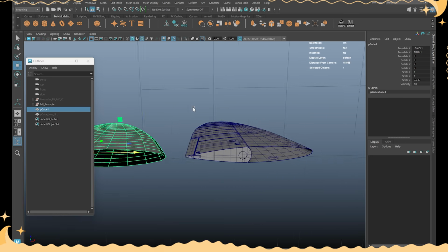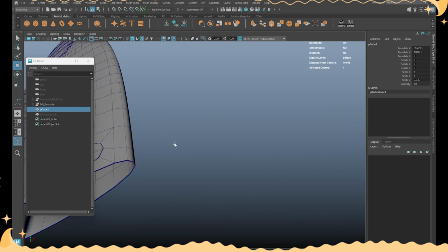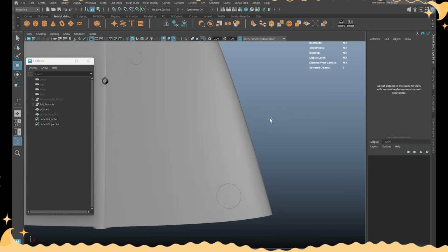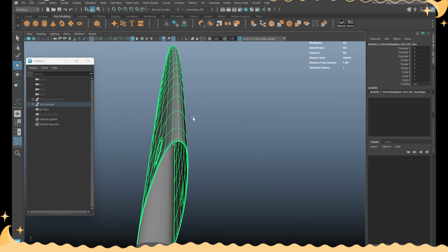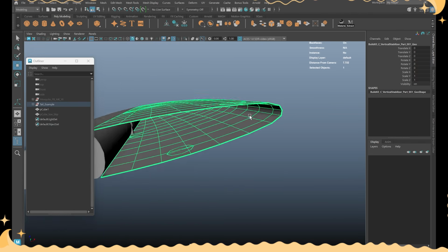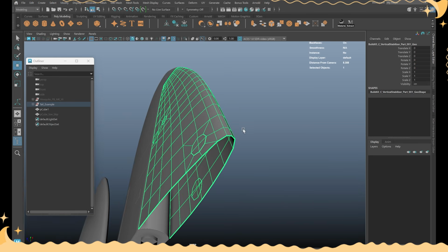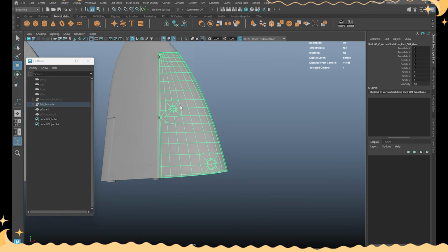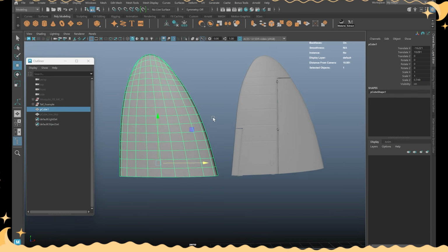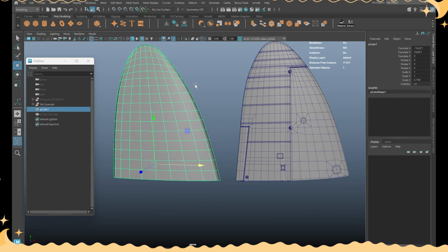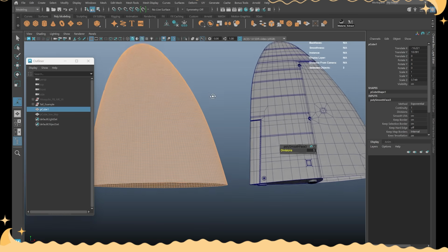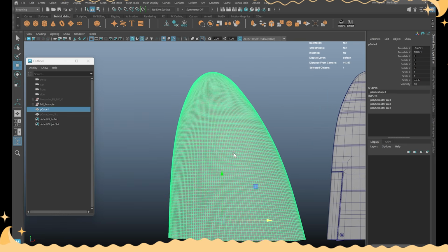You can see in my original version, it was kind of a bit more like this. I did not need that many subdivisions, just because the circles I did add here, the curvature is not too extreme. You can see there is a curve to it, but it's a lot more flat than other parts. It's not like it's at the front here, so we really didn't need that much. And that's one thing to look out for when you are modeling and subdividing: don't just go crazy and add a million subdivisions like this if you don't need them, right? Because this would just be excessive.